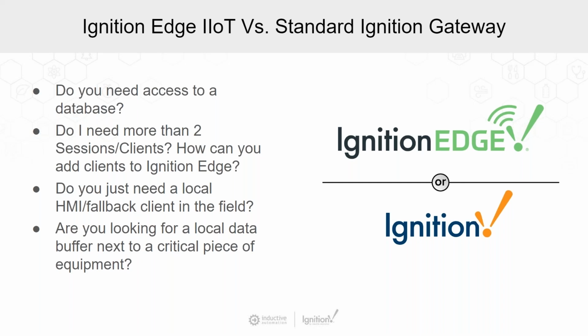Another question you could ask is, do I need more than 2 sessions or clients? And how could I add more? If you need more than 2, once again, standard Ignition is the right thing for you. But if 2 is going to be sufficient, then Edge is great. But no, you cannot pay for additional sessions or clients on Ignition Edge. You would have to be using standard Ignition.